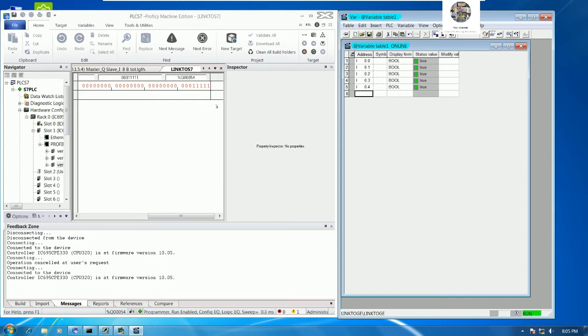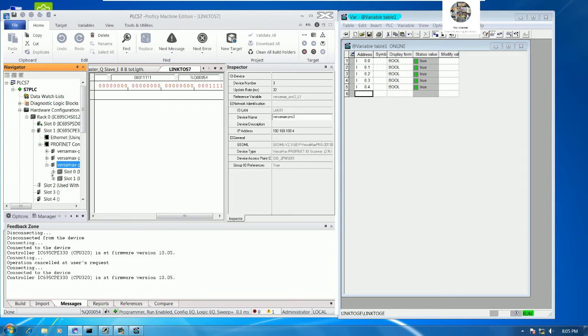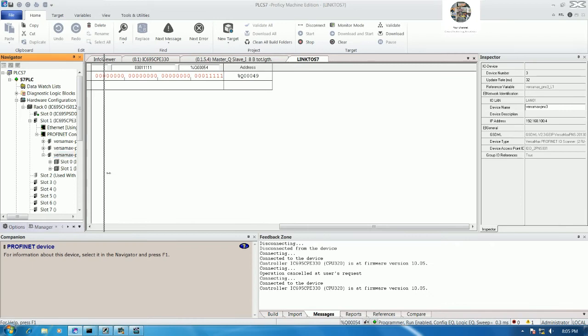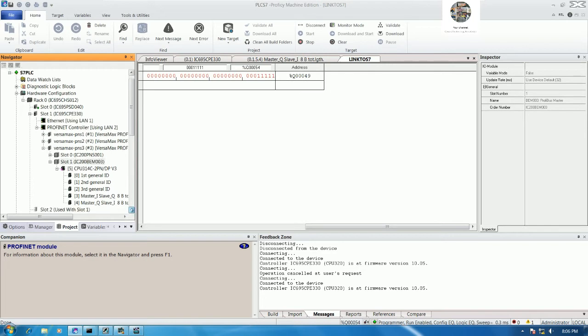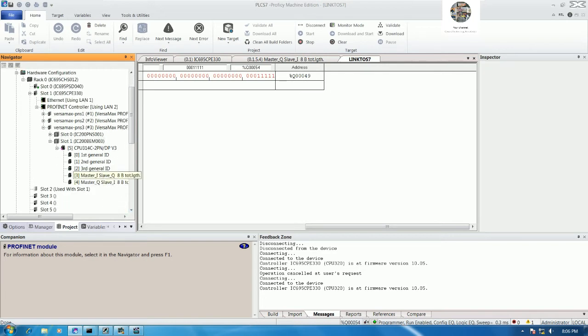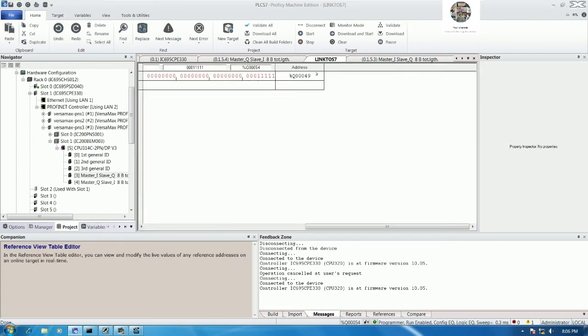And then we can force the signal. So let me check the input from PLC GE. It starts from the input board. So master in, right? So input 161, yes. So here we can choose option I161.